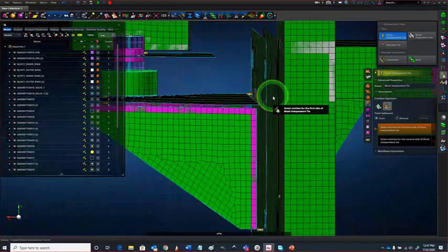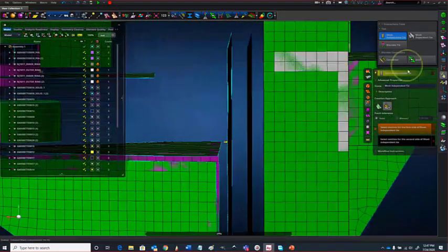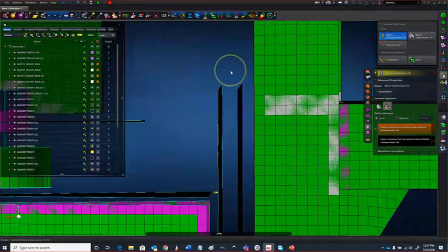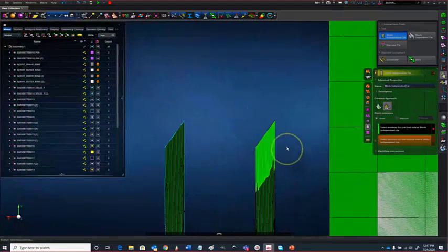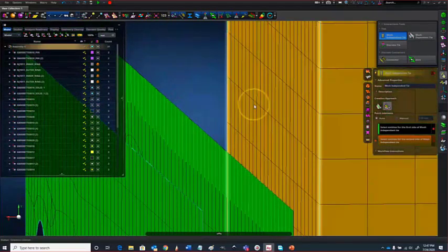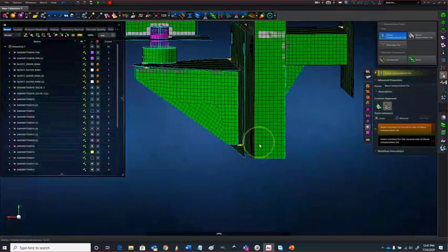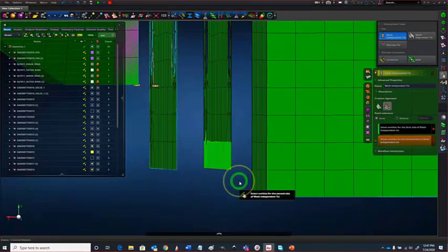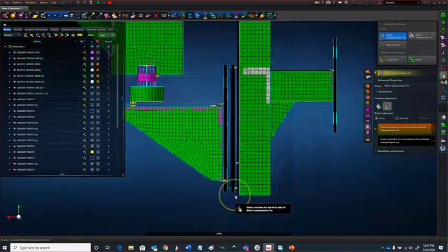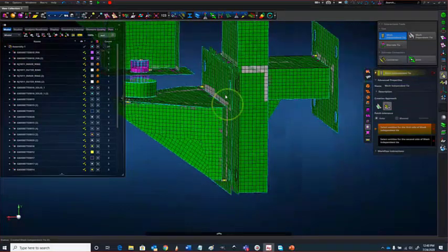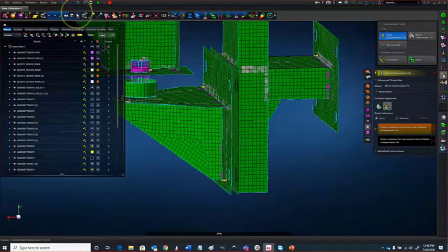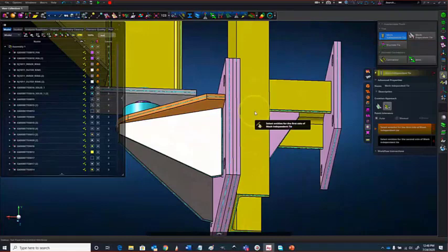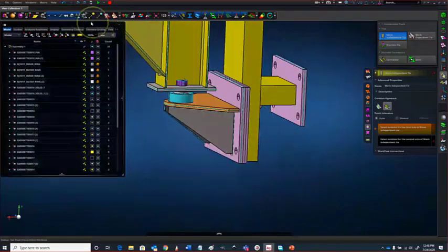And over here, I am just going to be a little bit lazy and only select the elements without needing to split the solid up, split the face again. So for that edge and this edge. So this is now a nice way to represent the fact that the plate will only be welded at the top where it connects to the beam at the back and welded over here. So let's assume it's not welded anywhere else.